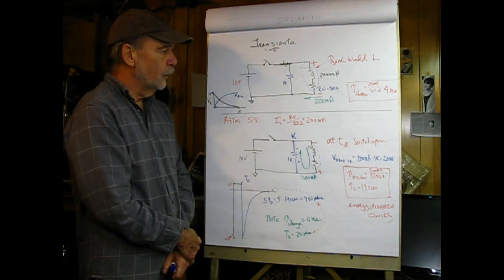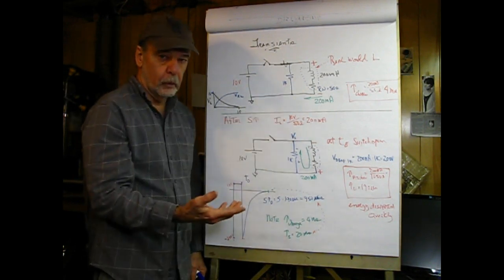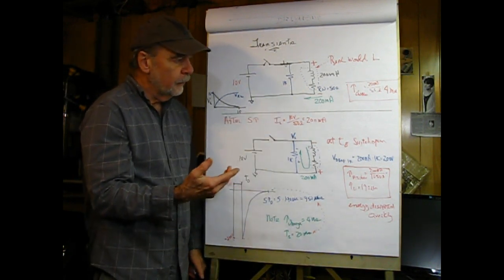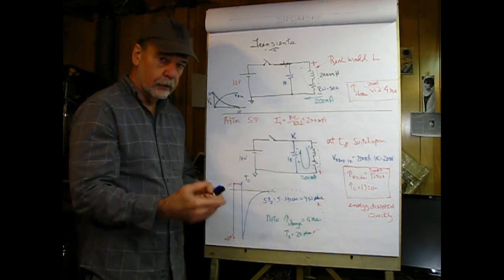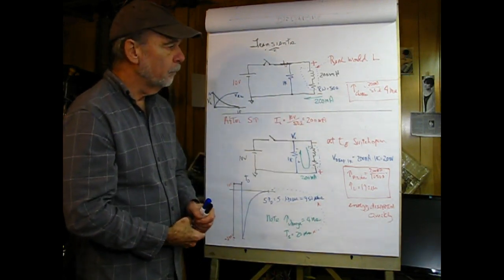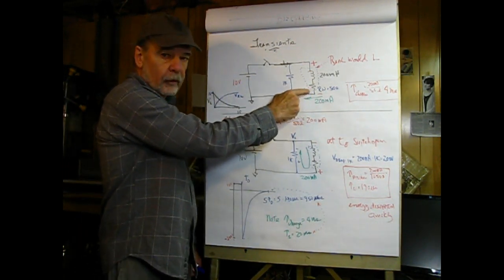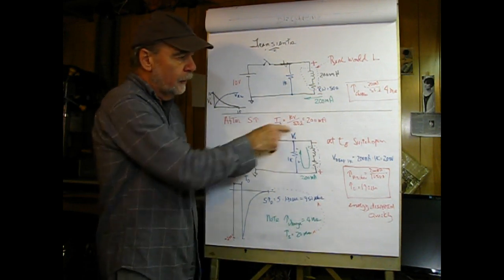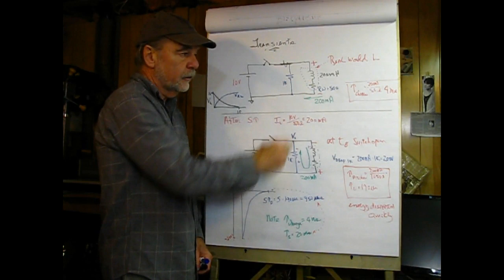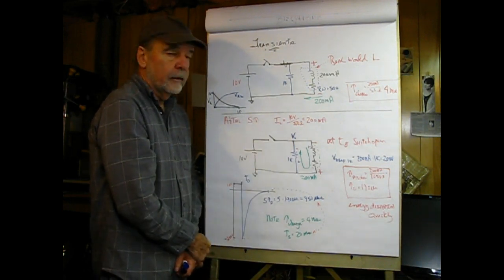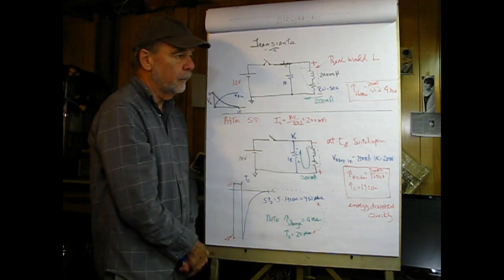So what we're going to do is charge an inductor, and in this case we're using a real-world inductance. The difference is that there's winding resistance because, well, wire has resistance and it's wound around the core, and the physical inductor is going to be a combination of both of these that I've indicated with a dotted line. You cannot segregate the winding resistance out of it and end up with a perfect inductor. The inductance and the winding resistance are part and parcel of the same physical part.